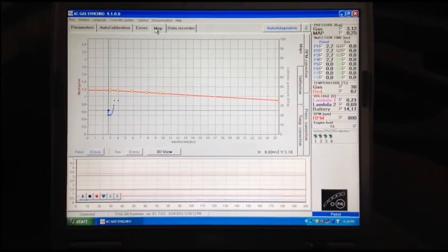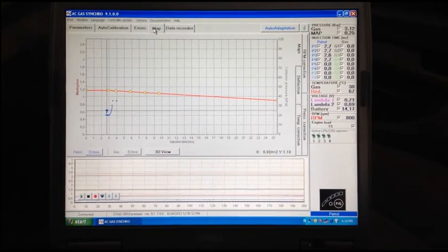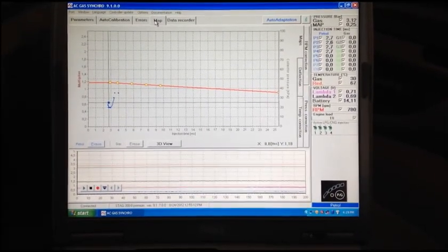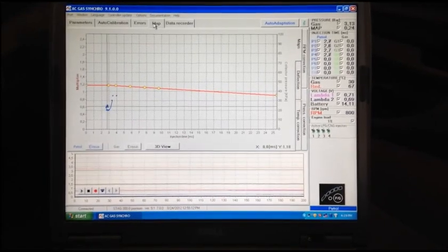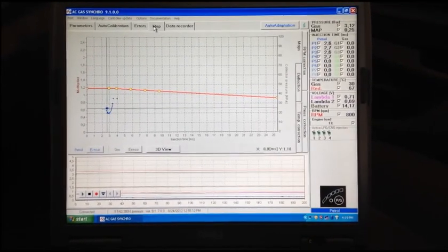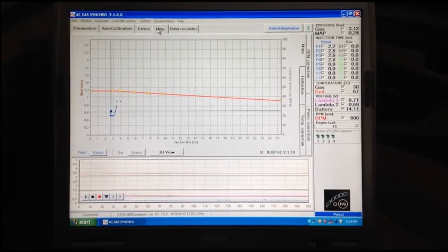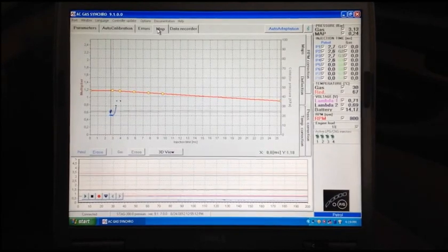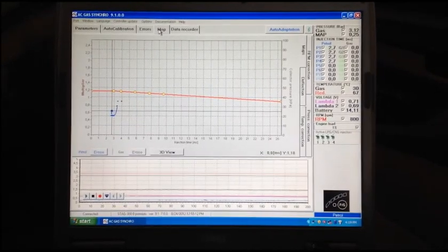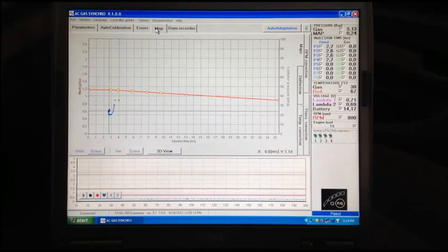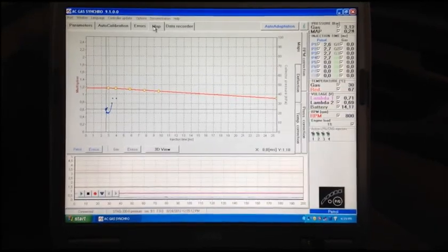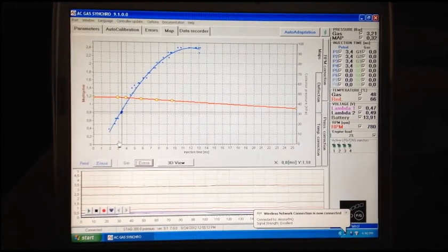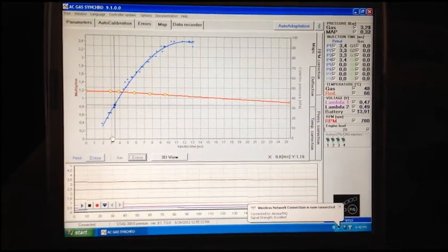So basically, that'll tell you that your factory computer, the gasoline computer, is making very small corrections to how you've got it set up properly, so that you'll have smooth switchovers and not a lot of correction in your fuel trims. Because if that graph is off very much, you'll get some errors like system too lean, system too rich, because the fuel trims have reached their limit and it can't correct any further, and that means your tuning is not right yet.